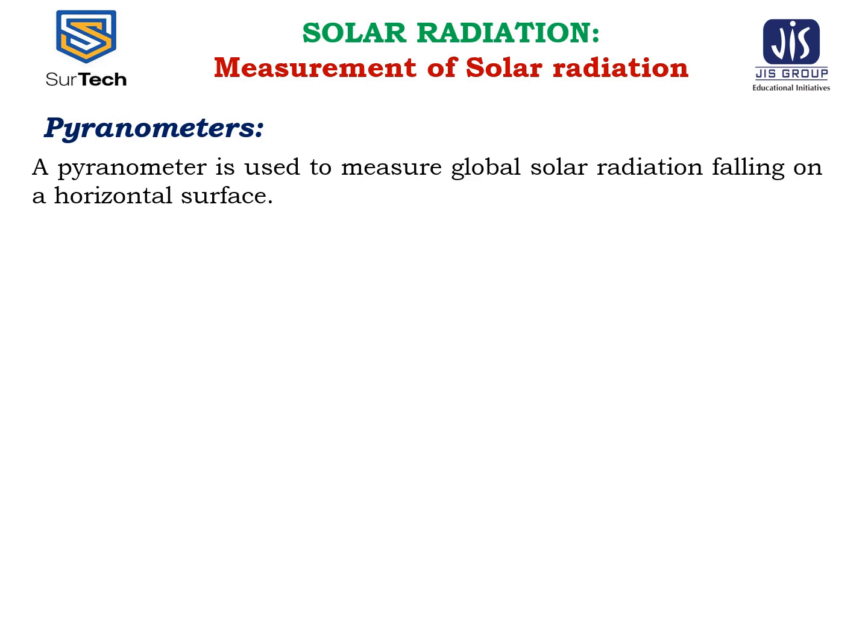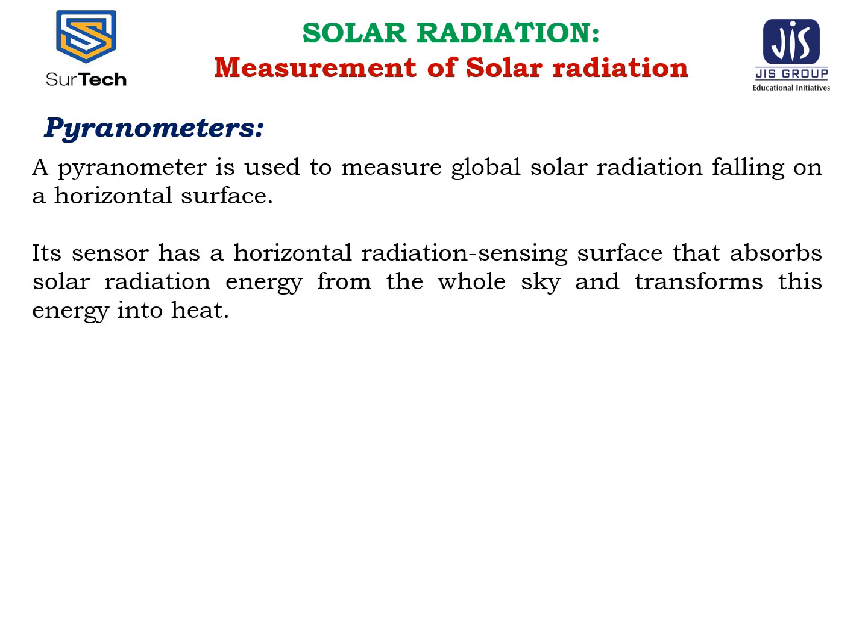Now come to the third instrument, that is the pyranometer. The pyranometer is used to measure the global solar radiation falling on a horizontal surface. In essence, they have thermocouple junctions, that is called a thermopile, under a black surface, all under a glass hemisphere. The temperature increase caused by the absorbed insolation produces a calibrated voltage.